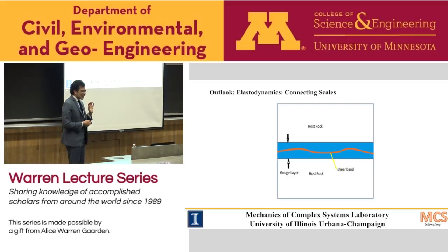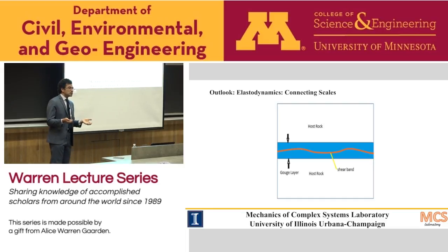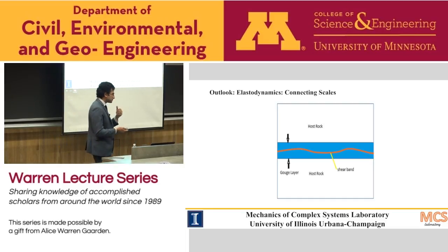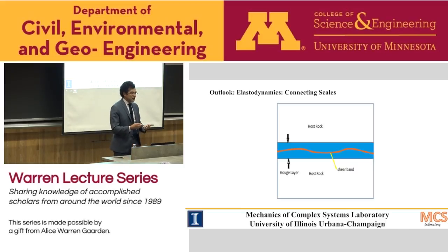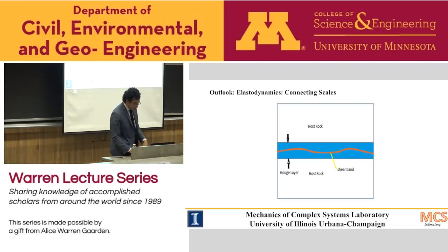And this is a daunting task because since the medium now is nonlinear due to the existence of the shear zone, we can only solve it with finite element or finite difference. And if we want to localize a shear band within an elastic material in elastodynamics, so we have wave propagation, we need to use very fine mesh, and we need probably to use this mesh everywhere in the system to avoid artificial reflection.